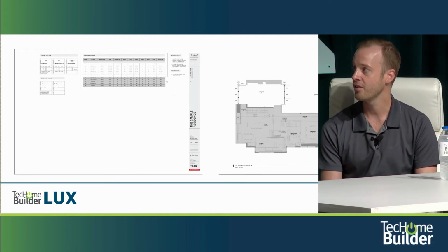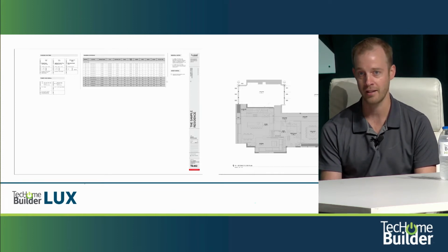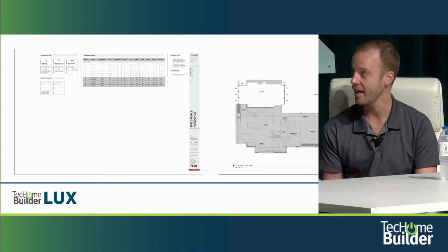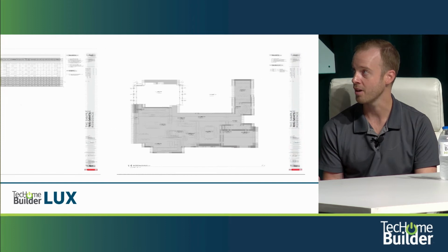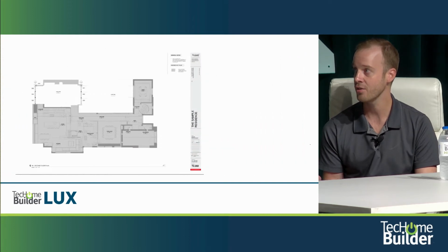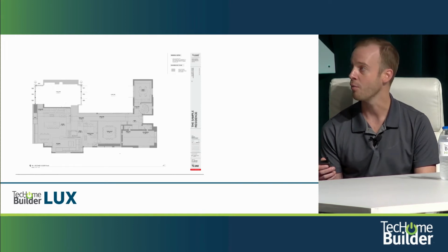And this is a level up of detail, right? You get shade schedules, you get lighting schedules, you get power and signal requirements, and this is all stuff that you guys should look for at this stage in the process, right? You get corresponding CAD level drawings, nothing's dimensioned. Technically, you could kind of build from this, right? Because you know what wires go where, what signal requirements things have, stuff like that.